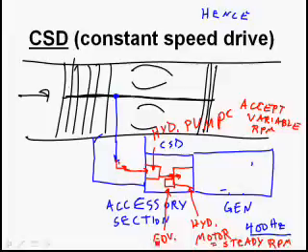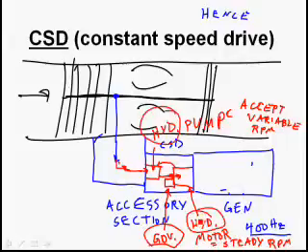RPM, because the governor is going to make sure that if it starts going too slow, it'll allow more hydraulic fluid to go in. If it's going too fast, it'll allow less. Of course, the fluid's going to come back to the pump, and it's going to go round and round. So constant speed drive essentially is a miniature self-contained hydraulic system that accepts a variable RPM from the engine, but keeps the generator, the AC generator, spinning at that one steady RPM.